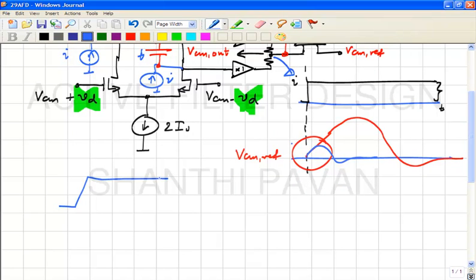So if this is the input, and there's a large resistor, how will it look? It will be this step multiplied by the large resistor. It will never go to infinity, correct? So the fact that you put in a step and you're seeing an infinite change in the output voltage means that the impedance has to have an inductive component. Does that make sense? Okay.